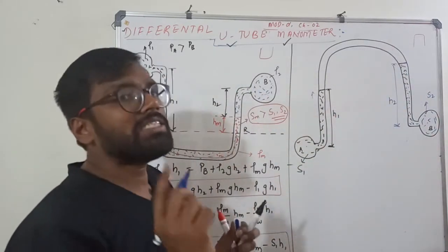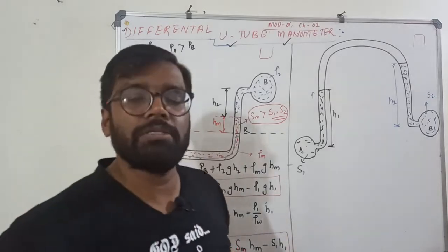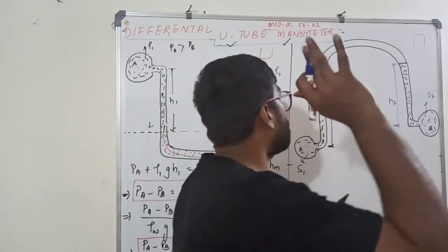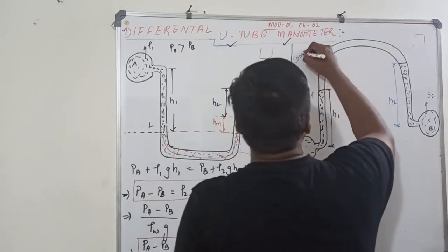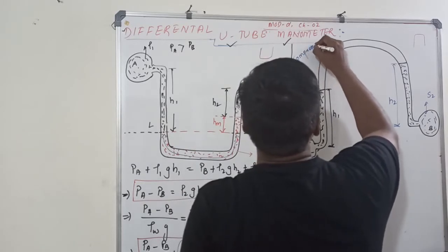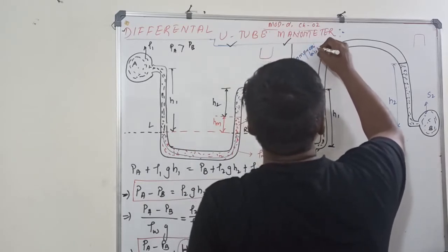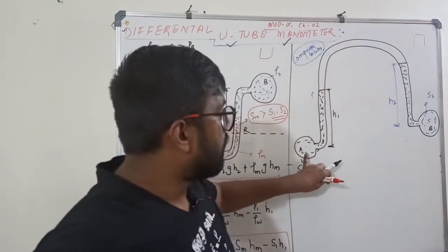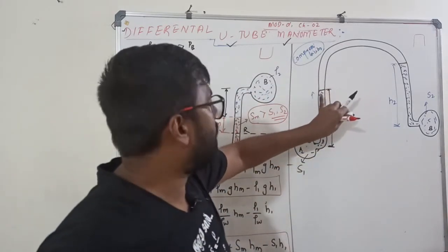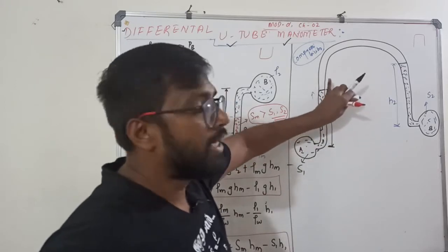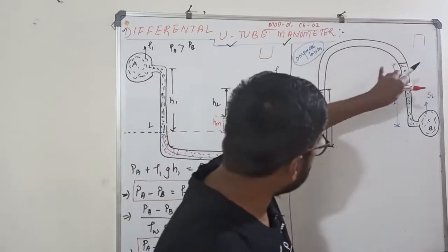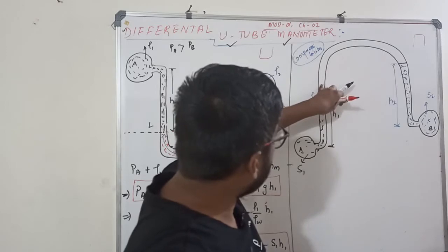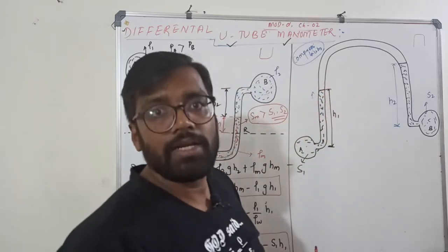But the problem is that air is compressible. What is the problem? Sir, the problem is compressibility. So when the liquid column on the left hand side applies a pressure, instead of transmitting the pressure, the air at A will compress.